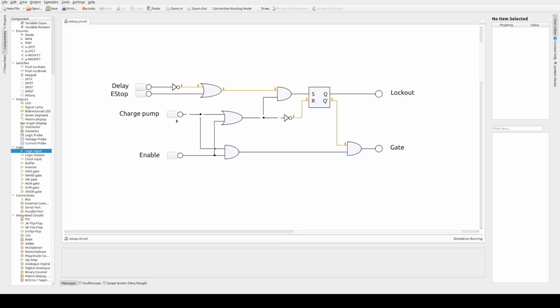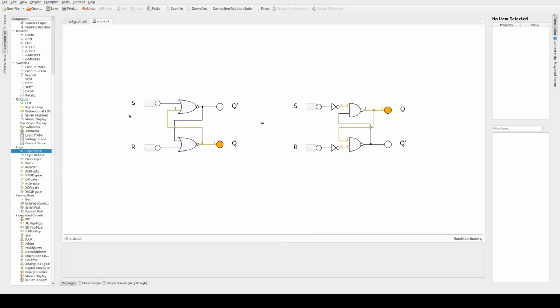We can get ICs with multiple ORs, ANDs, and SR latches, but if we do that and send this to manufacture, we'll get charged a pick and place fee per component type. So it would be better to have as few unique components as possible in our design. If we look at how an SR latch is constructed, it's either 2 NOR gates or 2 NAND gates plus 2 NOT gates. So it would seem like the NOR way is less components.